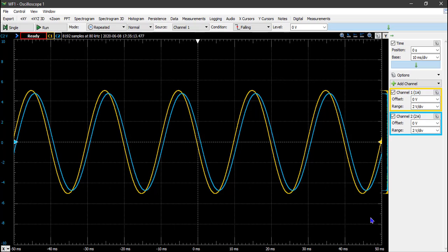Before we change the frequency of the sine wave and measure different output, we need to measure the peak-to-peak voltage of each one of these two signals, and then the time delay in between them. Because you're going to take the ratio of the two peak-to-peak voltages. That's going to be the magnitude of the frequency response function A(jω) for ω equals 50 Hz, and you're going to measure the time delay in between these two signals, and from that time delay you can calculate the phase difference, which is the phase of A(jω) when ω equals 50 Hz.